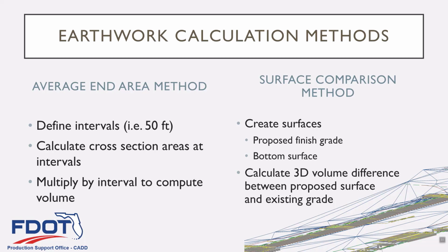includes pavement, so we're not going to really concern ourselves with it for earthwork purposes. That's definitely the one they want to use if they're using automated machine guidance for doing pavers. Then you probably need to build to that. But if you're just doing earthwork, you're doing grading, if you want to use automated machine guidance for that, you're going to need to look at that bottom surface. And if we're doing earthwork calculations, again, that bottom surface is the important one. Now, that's the reason we create it.